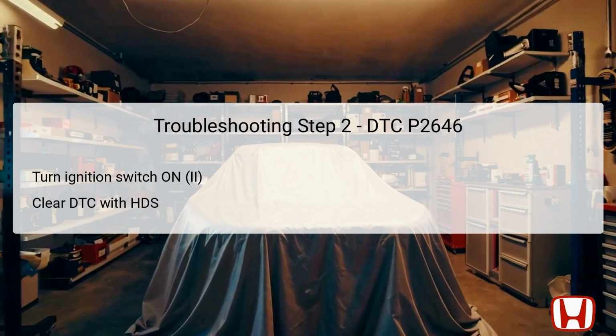Upon confirming that the engine oil level is adequate, the next step involves turning the ignition switch to the ON position. This is a key part of the diagnostic procedure as it powers up the vehicle's electronics without starting the engine, allowing the use of diagnostic tools.